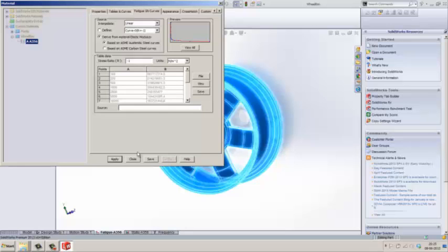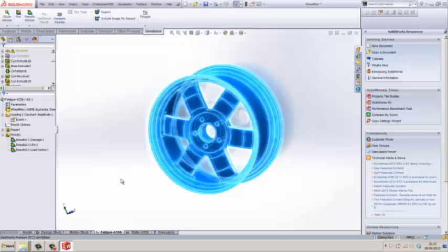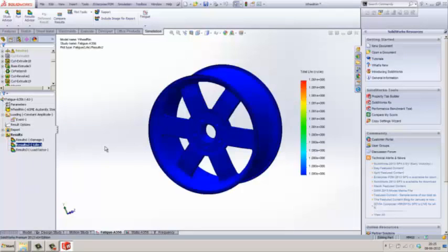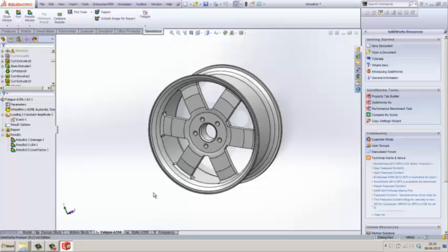If we have customized SN properties, we can feed them, else we can calculate them using the Young's modulus of the material. So this is the plot where we can see the total life of the wheel rim. If it is showing 10 power 5 or more than 10 power 5, then as per the theory we consider that it has infinite life.